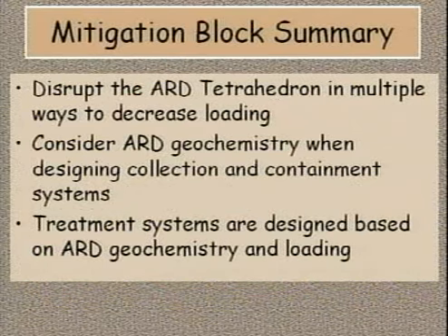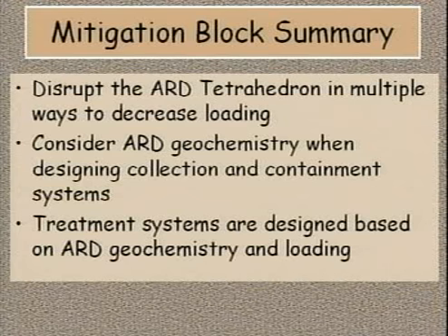Thanks for your attention. That was a lot of ground to cover in a short time. And hopefully when you encounter ARD on your next projects, you'll think first about, number one, how to prevent it by disrupting the ARD tetrahedron, and then consider the geochemistry of the ARD when you're collecting and containing it, and lastly, that the treatment systems will be sized based on the loading and the geochemistry of the water. If you have additional questions, you can email me or give me a call. And Dave, back to you.